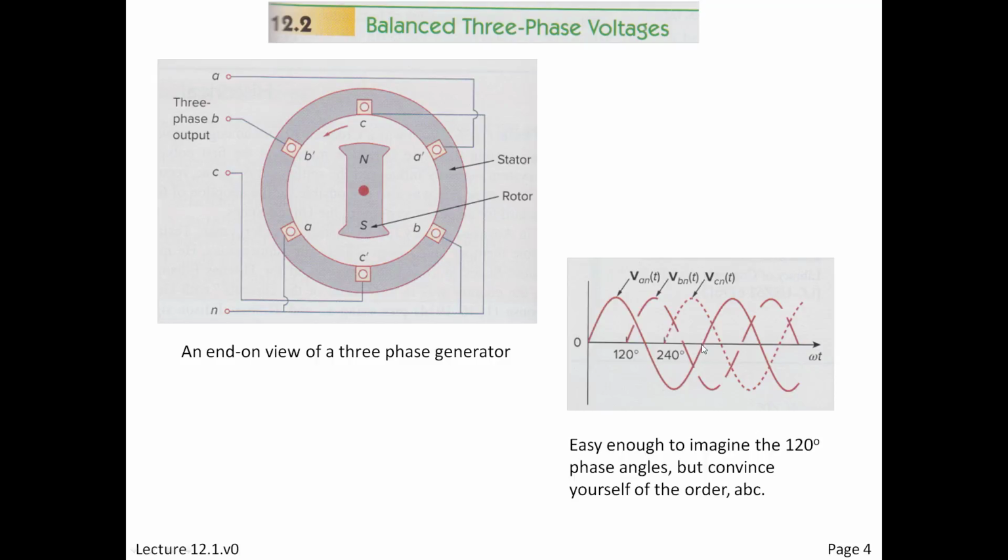Let's get down here further a little bit. Here comes A, and it starts up again now. So it's just past the A terminal, the A side. All right, and we could ask ourselves, where is C? Well, we're not aligned with C, but we're coming up on it. We're not 120 because we're 60 degrees out of phase with C. So this would tell me if I anticipate A is here, after the peak of A, 60 degrees later, I ought to have a negative peak of C.